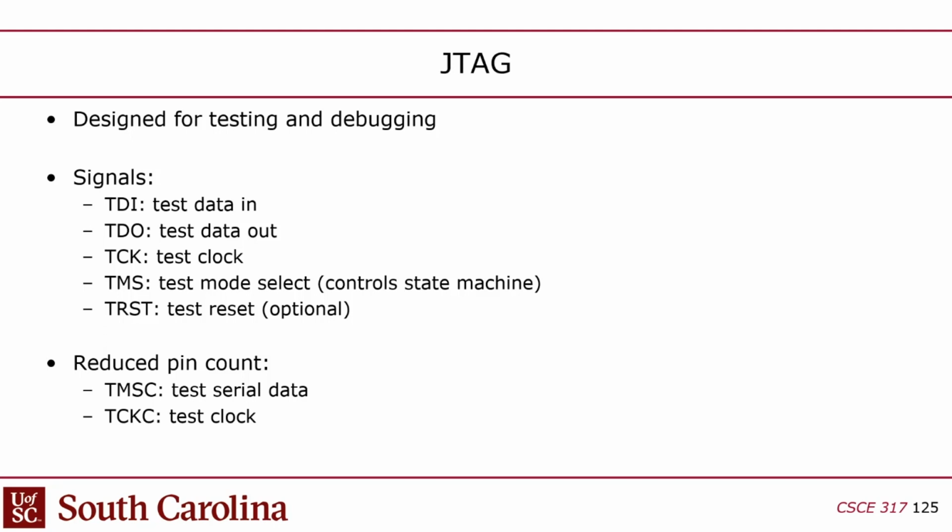This thing is actually a single bit signal that allows you to control all the slaves on the JTAG chain. Now the chain is actually formed from daisy chaining the TDIs and TDOs, which again is like SPI, how I showed you the daisy chained SPI. But JTAG is designed more specifically for that kind of chaining. And then there's a test reset, which is an optional pin. In my experience, JTAG's usually just these 4 pins. So there's 4 signals in the channel.